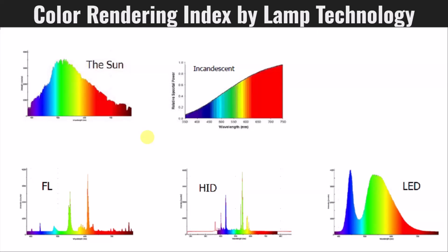Fluorescent lights also have phosphor coating. So that's how they get whatever color of white light. And again, the quality of the phosphors goes for uniformity and consistency in a space. Getting the same lot of lamps is very important for that. And that's why larger companies with bigger facilities replace everything at once, even if it's not end of life, to make sure that they keep the colors consistent, especially if there's branding involved.